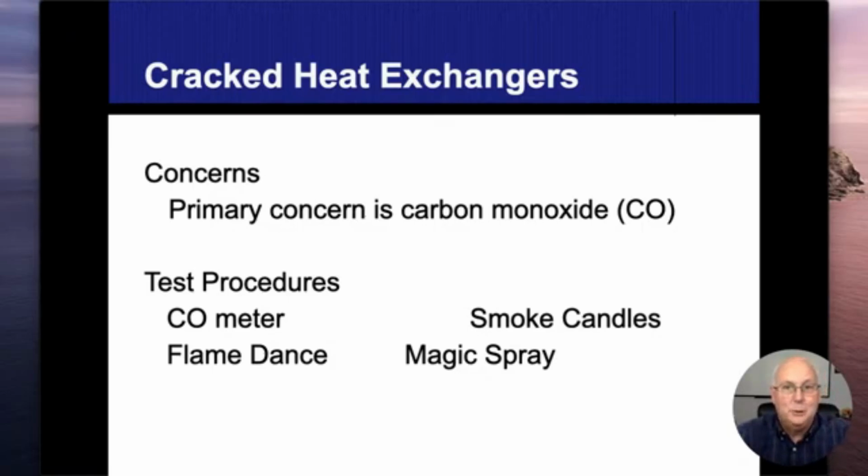The magic spray is kind of a joke a little bit, but it is an actual spray. I'm going to show a picture of it because I can't think of the name of it beforehand. It has a lot of alcohol in it, and it is very flammable. I've seen it work where it actually showed a hole or a crack in the heat exchanger. So with this spray, with the furnace running and the burner going, you actually put the spray into the blower fan of the circulation air. When you spray it in there, like I said, it's very alcohol based, so it dissipates quickly.